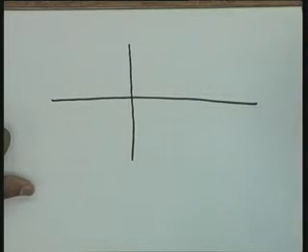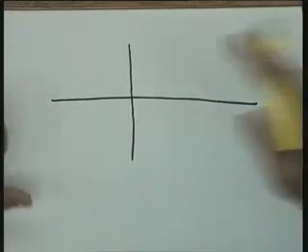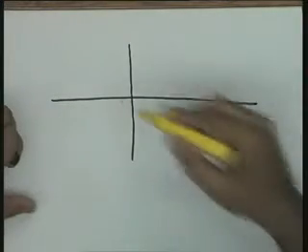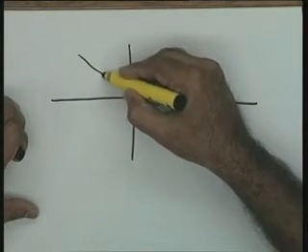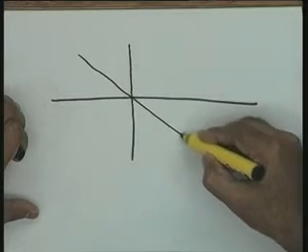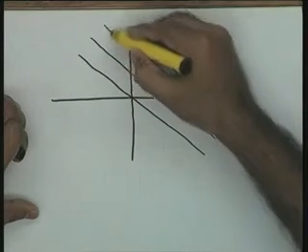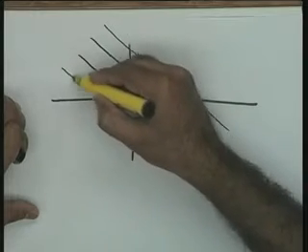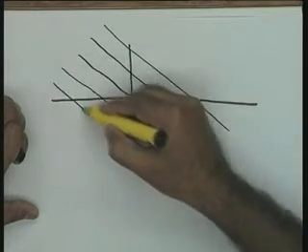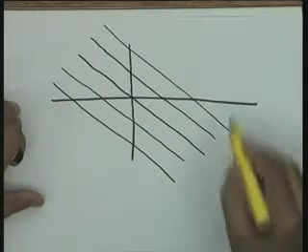So you have to suitably take the operating point on those characteristics and take the slopes K1 and K2 around that operating point. So, instead of giving you the total nonlinear characteristics, let me take the linearized version. After all, I have already made an assumption that the perturbation around the equilibrium point is small, and therefore I am taking a linearized version of my characteristics.